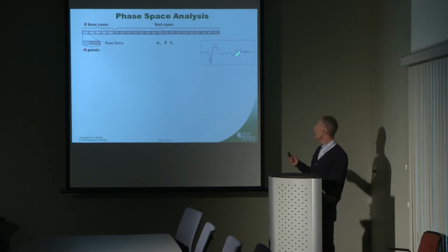And here's a snippet of real brainwave data. And what you see here is this is an eye blink. And so what has to happen is we apply the artifact filter to remove that eye blink, which is the green, and subtracting the green from the blue, one gets then artifact filter data, which I call GI.